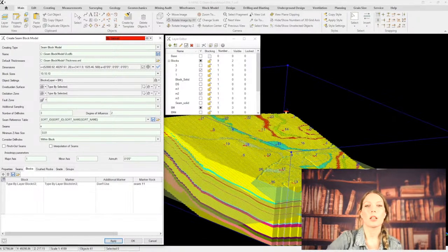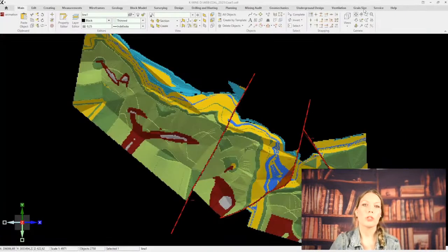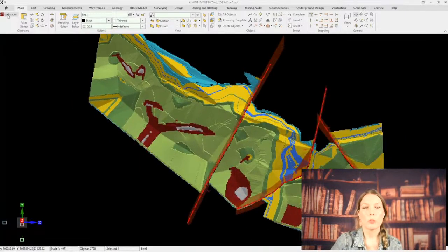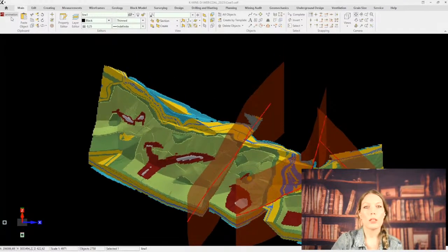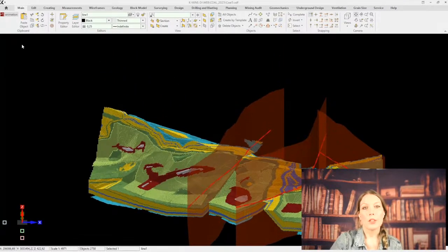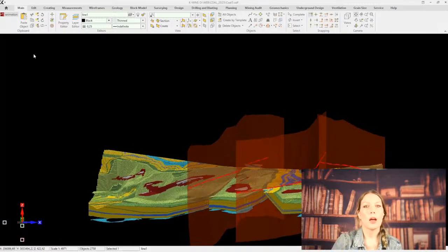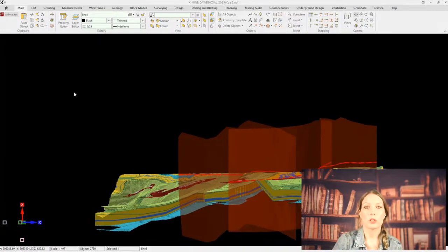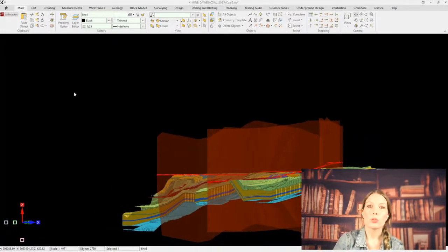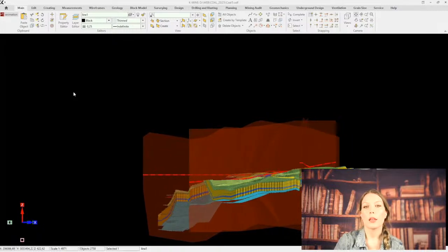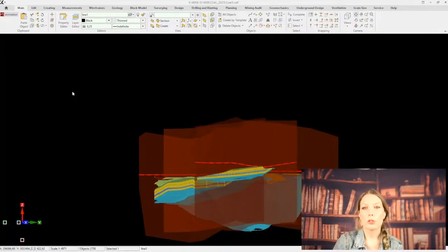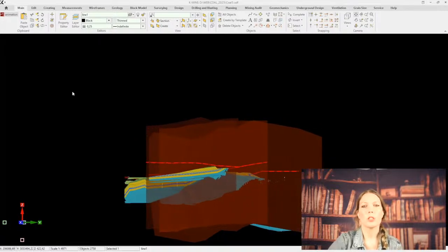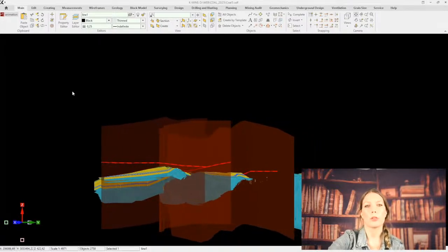Layer thickness is calculated using the inverse distance weighting method, and users can refine the interpolation by adjusting the number of drill holes considered or modifying the weighting exponent. Additional modeling settings include anisotropy parameters for directional searching, contact validation tools to refine layer boundaries based on known values in exposed areas, and auto customization options to enhance model accuracy.